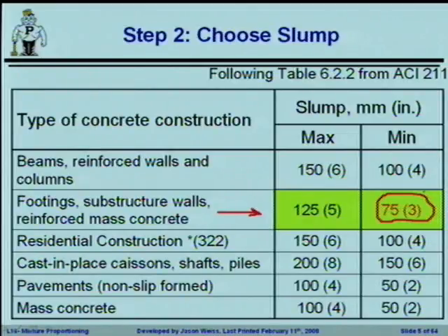What are some of the things you need to consider before you select a slump? Water to cement ratio? No, that was wrong. Not water to cement ratio? Where you're going to be placing it, who's going to be placing it, what equipment they have to be placing it, how easy it's going to be, what's the level of congestion that you expect with the reinforcing bars.